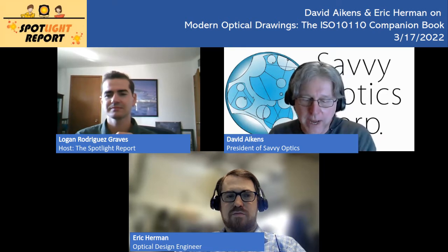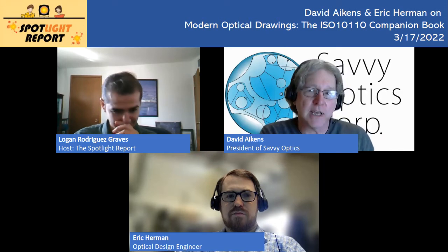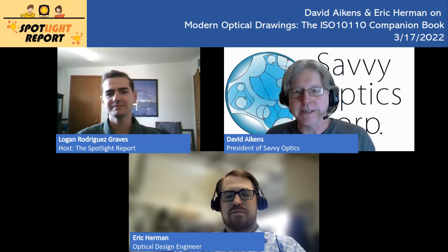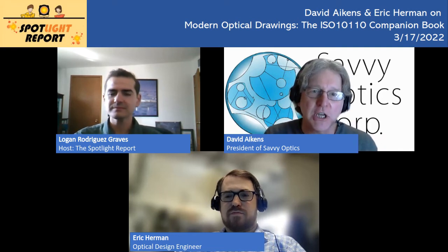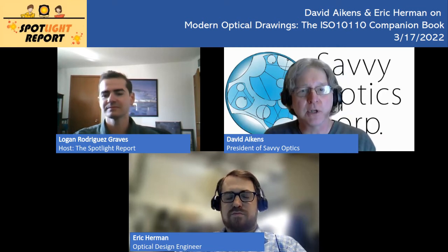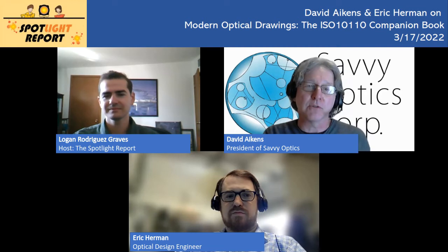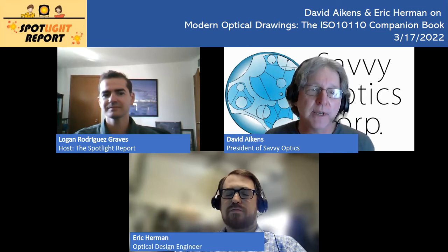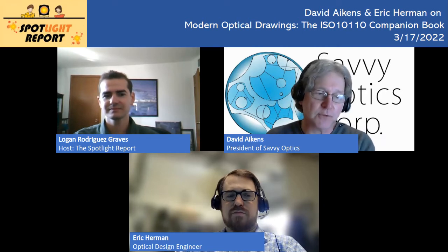So defining where roughness ends and waviness begins, or where waviness ends and form begins, is actually really application specific. Each application and each lens might have a different boundary for those conditions. In the lithography world, what they call waviness, most people would call roughness. They go way down into the really micro spatial frequencies, and they specify how much undulation you can have all over the surface.